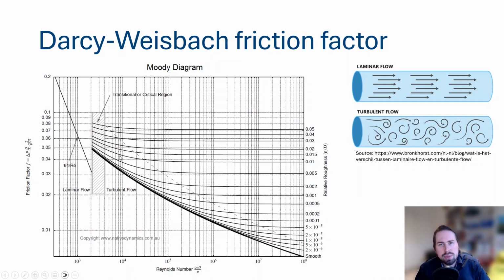And there you see that the friction factor decreases only slightly with the Reynolds number, and after a certain amount of time it stays constant. Now typically in your geothermal systems you do not reach this point. We typically have systems that are around this turbulent laminar zone, this transition zone. So this is typically where we work.